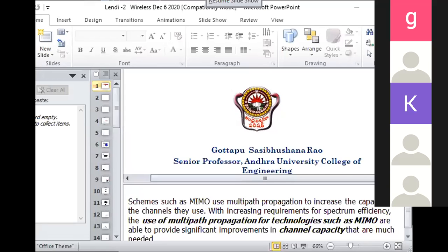If the channel condition is good, I may go for 64 QAM or 256 QAM, with higher and higher data rates. I can provide that particular user 1 Gbps speed easily by using 64 QAM. Suppose the user is residing in a multiple buildings area, then my channel conditions are not good.